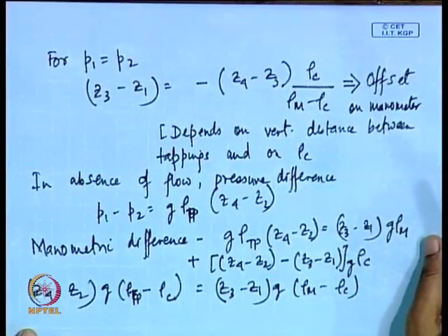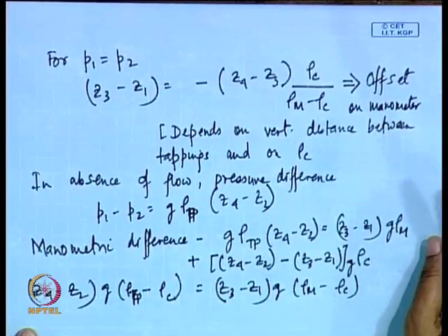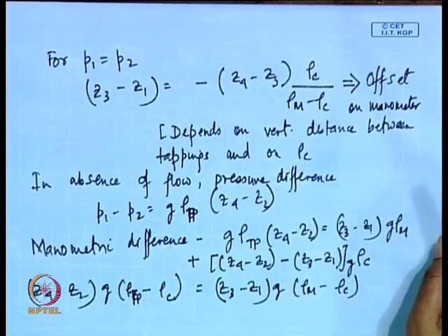lines. But the pumping action is so very high and the tendency of liquid entering into gas filled lines is so very drastic that for most of the cases we do not prefer gas filled lines, we prefer liquid filled lines, unless some very special circumstances or applications force us to adopt gas filled lines, correct. So, therefore, this was pressure measurement with manometers.